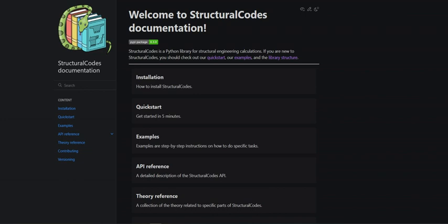And then when you go back down to where you're defining where your reinforcement sits, you've got your cover and your diameter, and then how is it defined, sort of your horizontal position of the bar? Oh yeah, I see here. Right. Okay, gotcha. So I skipped the names of the keyword arguments here, but these two are in this function call, add reinforcement. It adds a point at a given coordinate.